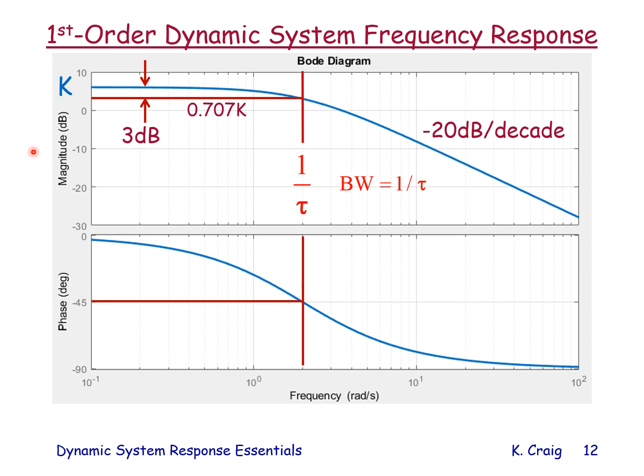We plot them on a semi-log axis, where the log scale is along the frequency horizontal axis. In the amplitude ratio, it's dB, so it's linear in dB. And in the angle, it's degrees, and it's linear in degrees.